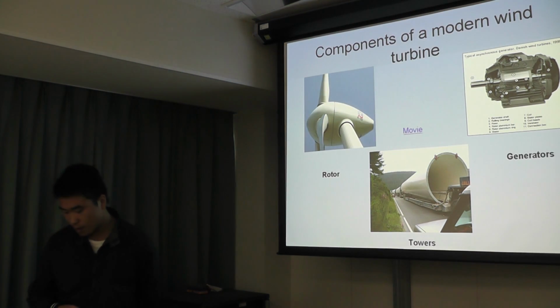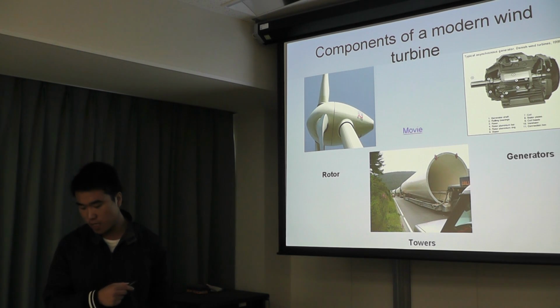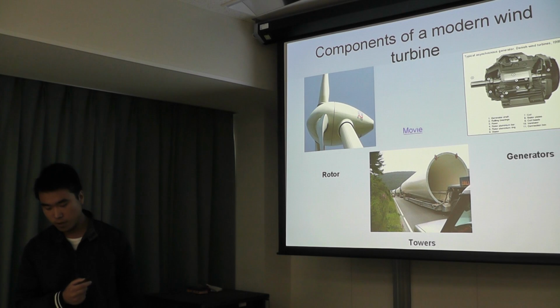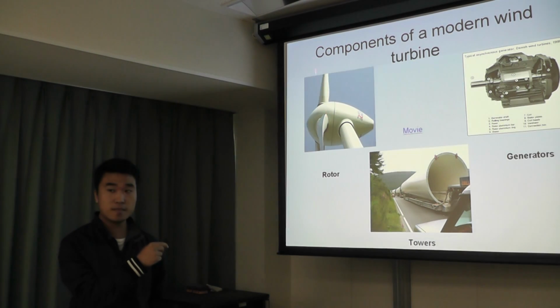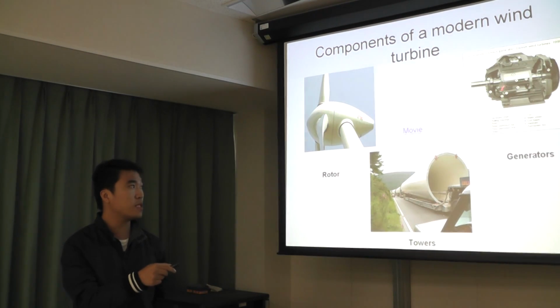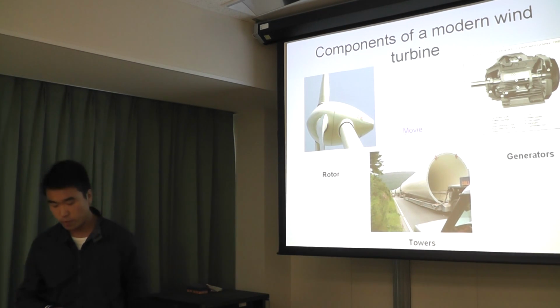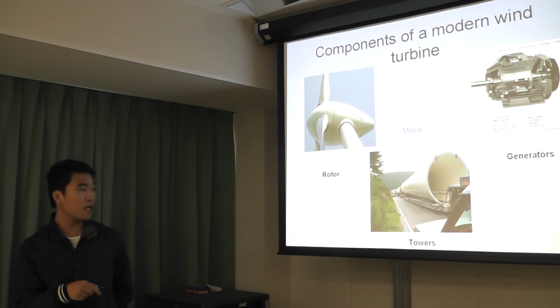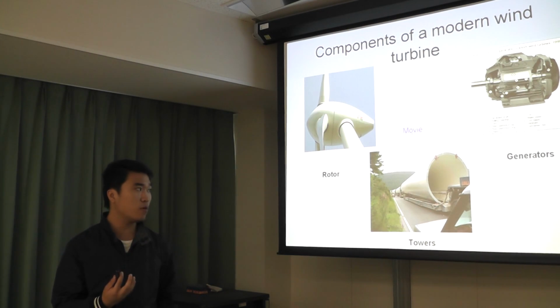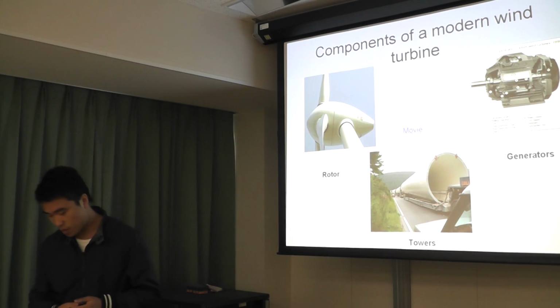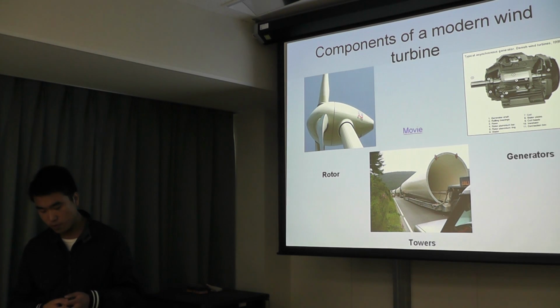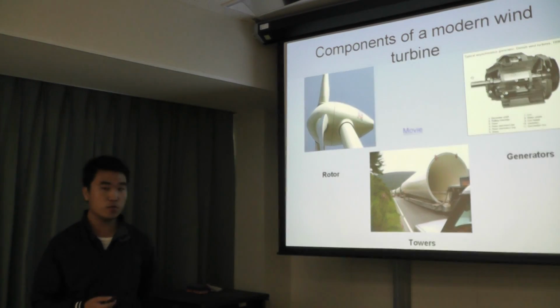They are available in a large range of output power ranges. The generator's rating size depends on the length of the blade. It means that if the blades are longer, it will generate more powerful electricity. And the last one is the tower. Research shows that if the tower is taller, the wind speed is faster. So if you want to generate a huge amount of electricity, you need to build a very tall tower. Large turbine blades usually range from 40 meters to 70 meters.